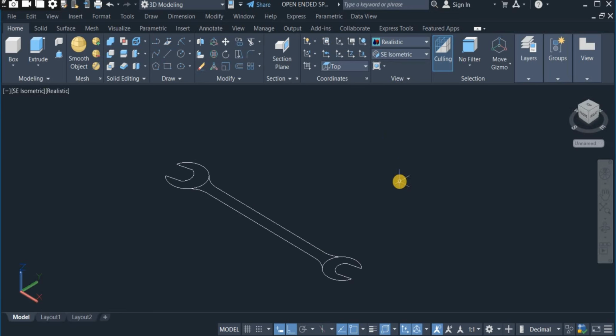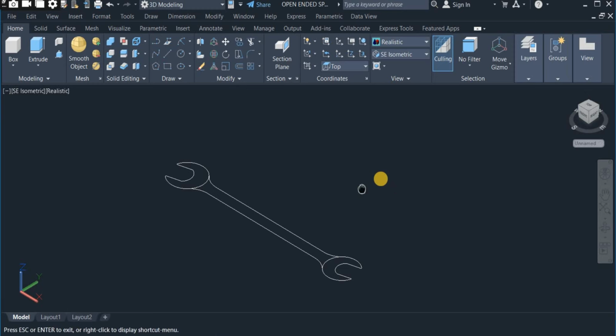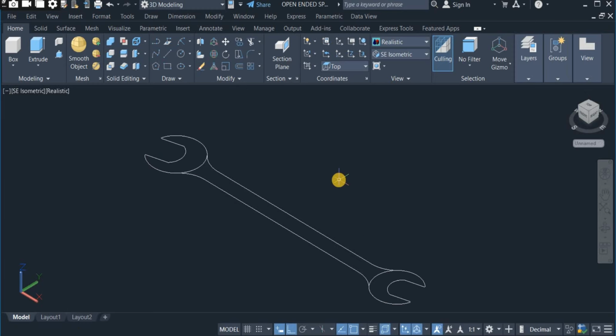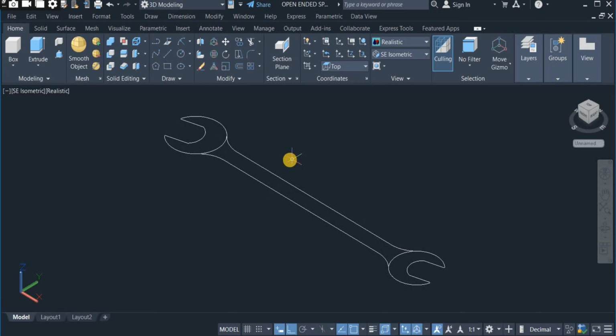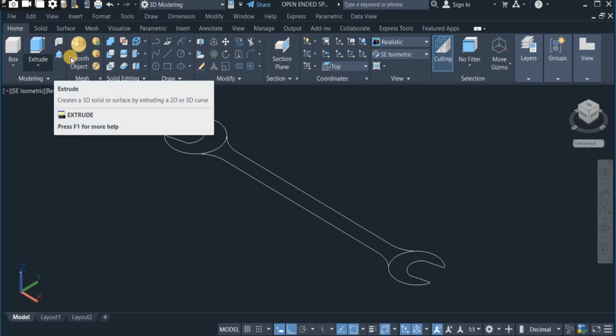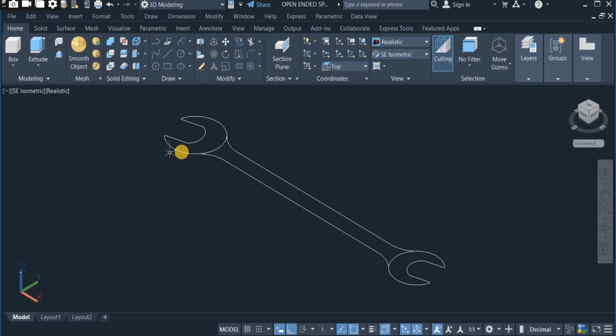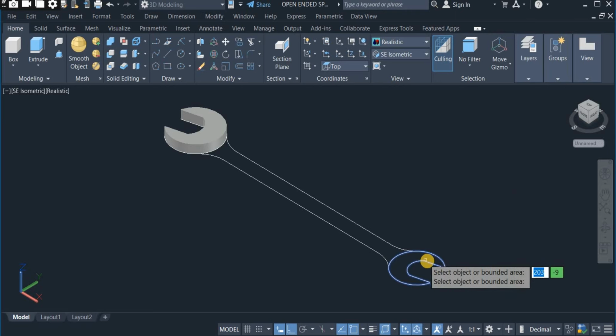Okay. Okay, so this is the isometric view. Now I'll now begin to use the extrude command to extrude, or use the press pull command to pull. Both of them will give me the same result. So I'm going to extrude this, or rather press pull it to a height of 7. So I click on the press pull command and click here and pull it up by 7. Also pull here up by 7.